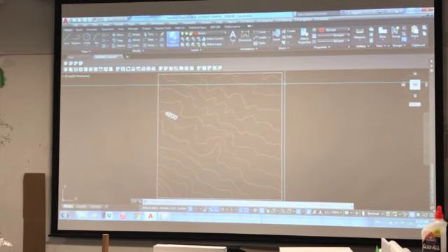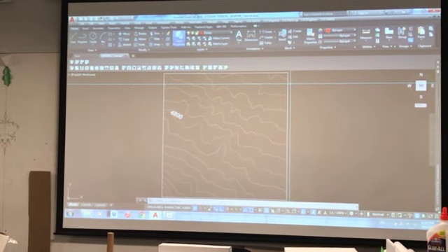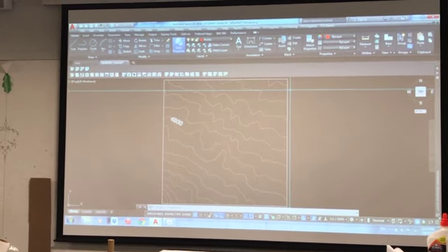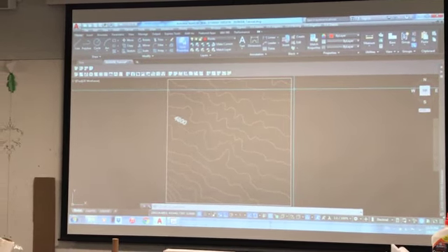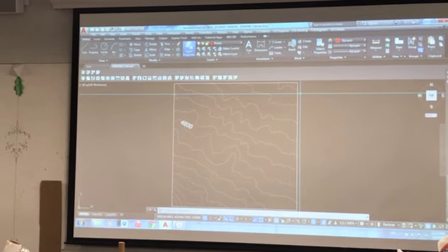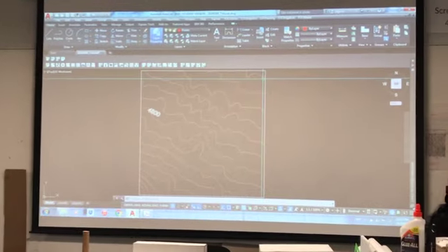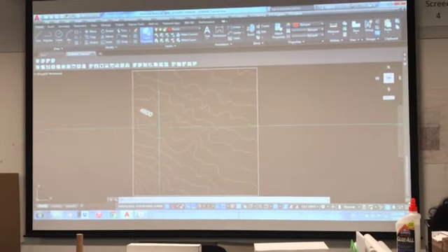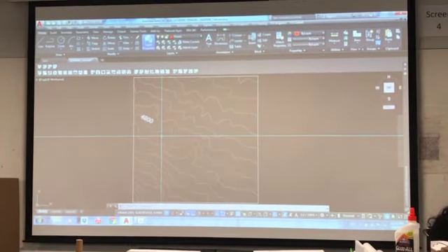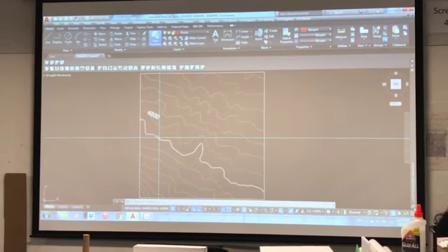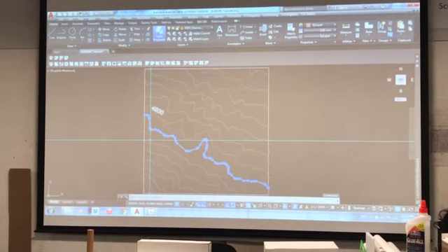I guess you would call them the arcs of the wavy undulations would typically go downhill. Sort of, yes. It has to do with the geometry of the lines themselves. If this one is 4800, and these are 40-foot contours, so the next one higher is going to be 4840, okay?